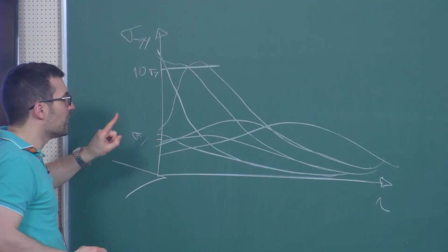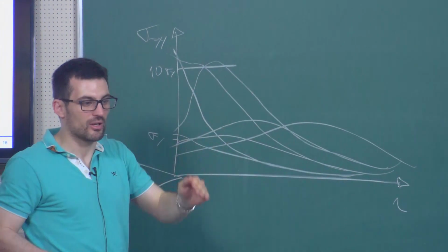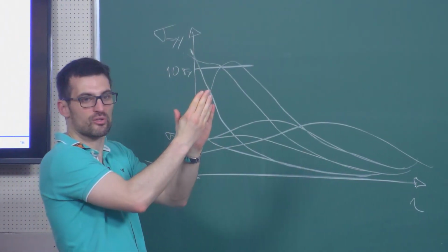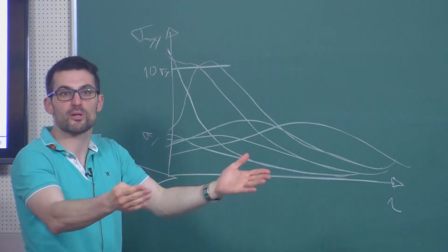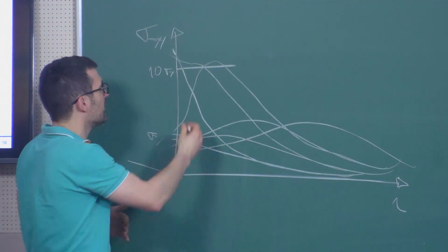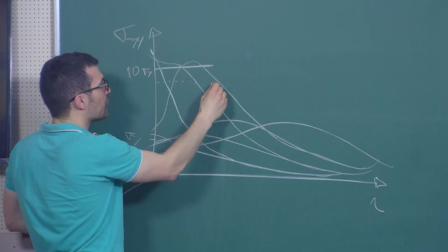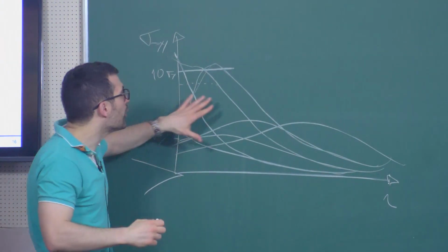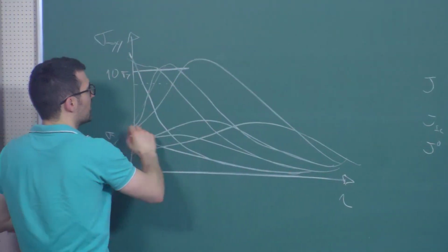That being said, what happens when you have hydrogen, for example, or a brittle material, a ceramic interface? The ceramic interface basically blocks dislocation emission, so you get a little bit more stresses. In low temperature cleavage, you lower a little bit your fracture energy. When all of those things happen, basically this thing goes down. So now this curve is going to be big enough.